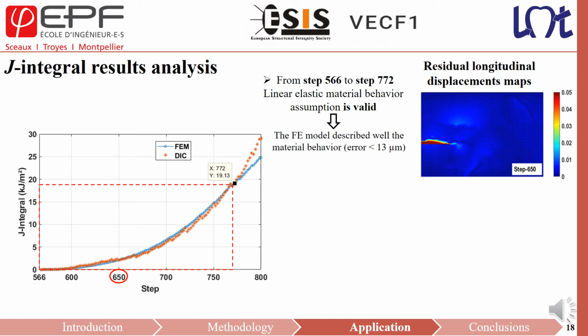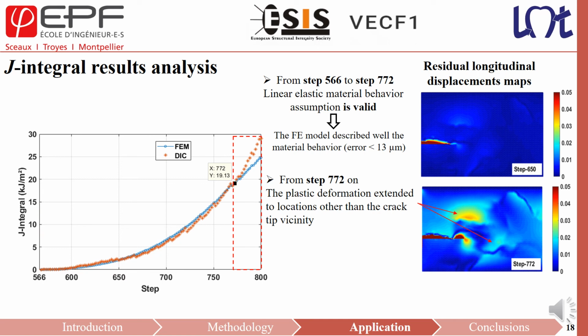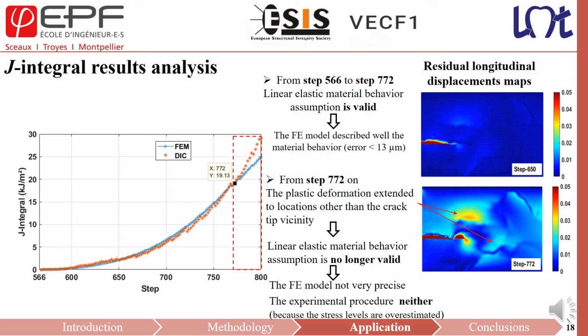From step 772 on, the plastic deformation extended to locations other than the crack tip vicinity, which made the FE model not very precise because it did not take into account the plastic behavior. This is also true for the experimental procedure, in which the stress levels were overestimated.